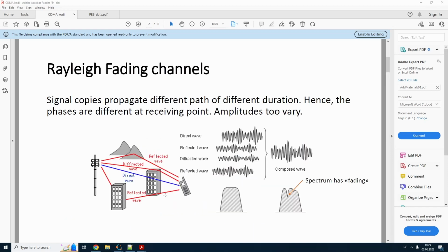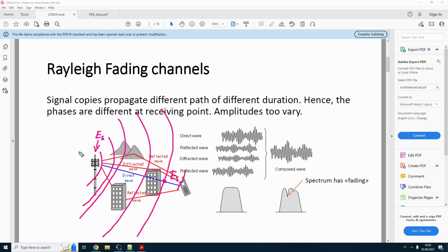We don't really want to do that, because what happens in the sense of transmitting data is that the transmitter has some kind of energy per transmitted symbol, let's say the energy of the symbol. This energy is distributed: the further your signal travels, the less and less energy arrives at this point. So basically this energy of the symbol is distributed in this sphere. Well, maybe not exactly a sphere for real antennas, but we still need to consider some area of the effect of this antenna, and at this point we are going to get only part of the energy. The same part as would be here, traveled by this path. It also has part of the initial energy, and this also has part of the initial energy.